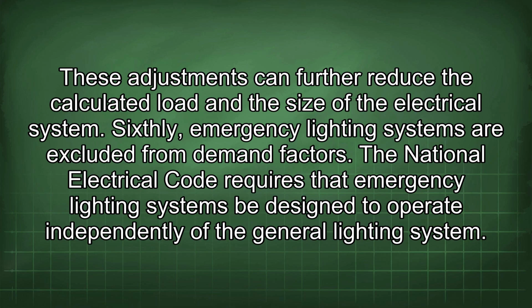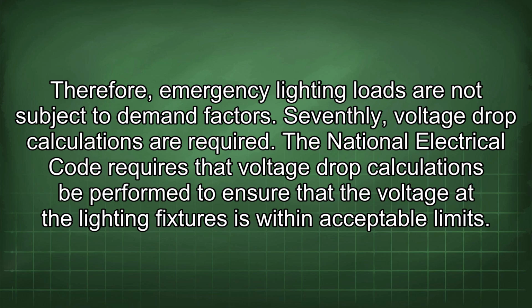The National Electrical Code requires that emergency lighting systems be designed to operate independently of the general lighting system. Therefore, emergency lighting loads are not subject to demand factors. Seventhly, voltage drop calculations are required.